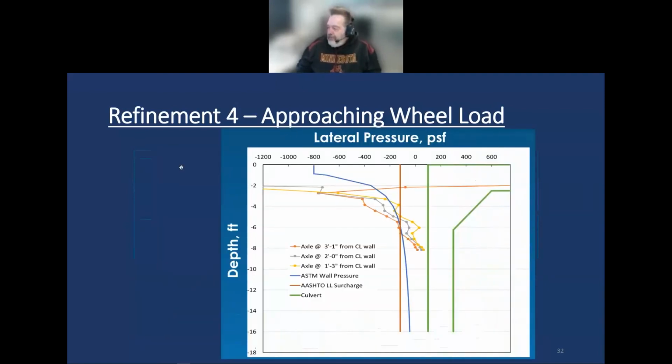They had this graph in their report, and it's a little goofy to look at, but think of this green section as the outline of your culvert with no fill over the top. This represents your culvert, and it has incredibly deep fillets, if you will. It goes from a little over 2 feet to nearly 6 feet, so 4-foot fillets are pretty ginormous. But what they're trying to show here is that if you put axle loads on a continuum model, it will generate horizontal pressures on the structure itself.